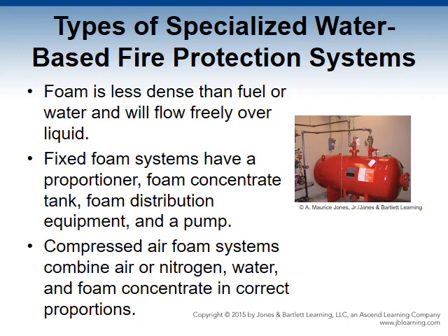Fixed foam system components. Let's look at that right quick. Many components are the same as those used with other fire sprinkler systems. Additional components are necessary, of course, to generate the foam for the fixed foam systems. The proportioner mixes the foam concentrate with water and sends it through piping to the foam generating discharge devices for application on the fire. And it's proportioned in three basic ways.